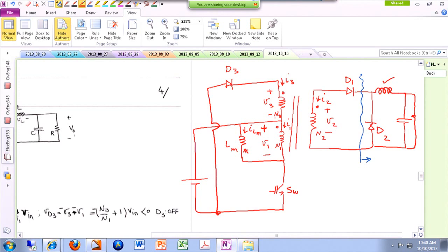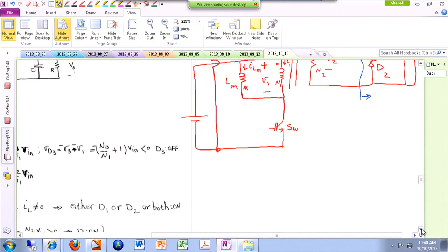All right, we are going to go ahead and analyze this converter. Similar to before, we are assuming that our period starts when the switch is turned on. If you look at the gate command applied to your switch, it is on at the beginning of the cycle, then off for the remainder of the cycle. The on segment is duty cycle times period. This is our first mode, and this is our second mode, where we have off.